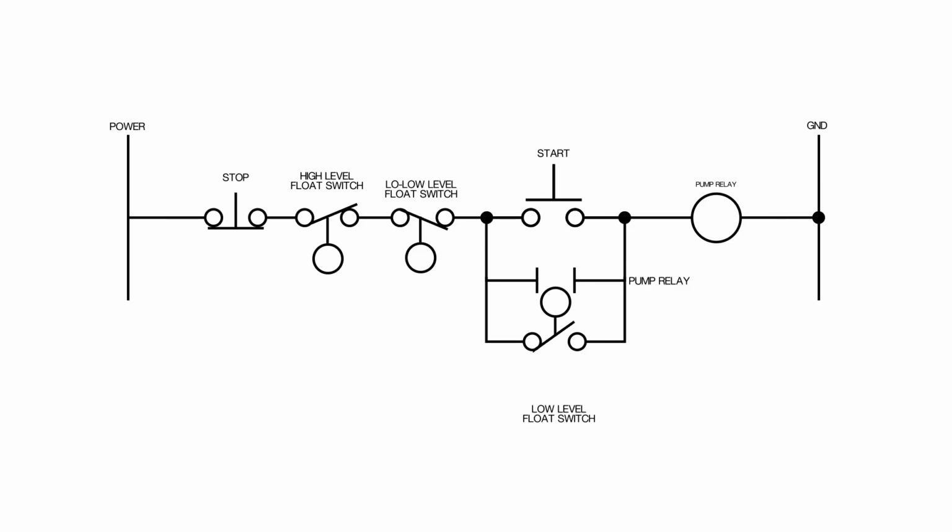When enabled, the pump will turn on automatically when the liquid level drops below the low-level switch in the processing tank. The pump will remain running until the liquid level goes above the high-level switch in the processing tank, or the operator presses the stop button. To prevent damage to the pump, if the level drops below the low-level switch placed at the bottom of the supply tank, the pump will shut off.